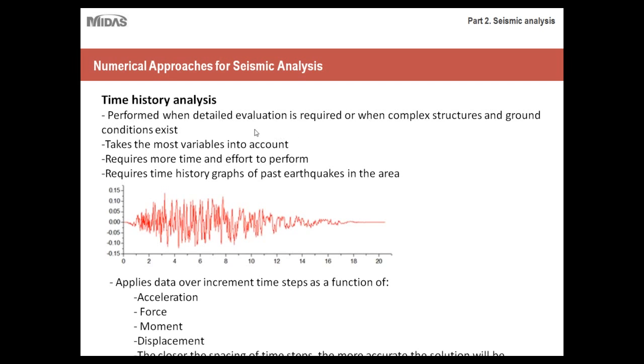So I mentioned analysis that's done in California, Washington, Alaska, Hawaii. Most engineers that I'm acquainted with there typically deal in time history analysis for almost all of their projects, just because of the high seismic region that they're in, and also for the larger scale projects that are built there. Time history analysis is their only realistic way to design for the seismic loading that takes place there. So it takes the most variables into account.